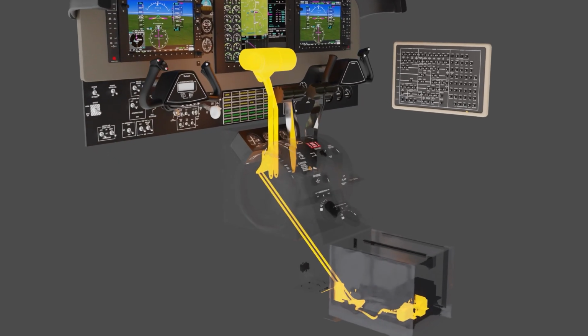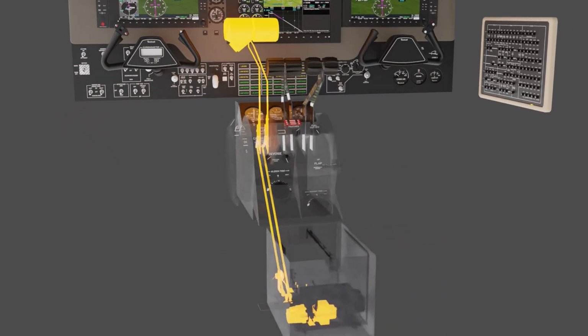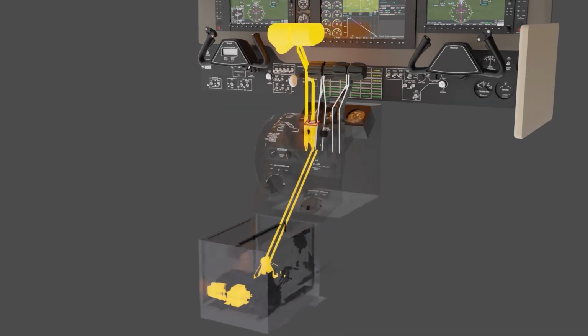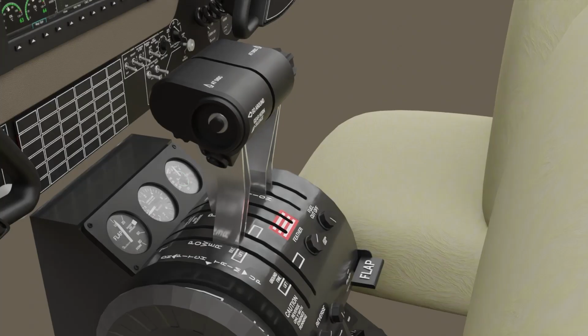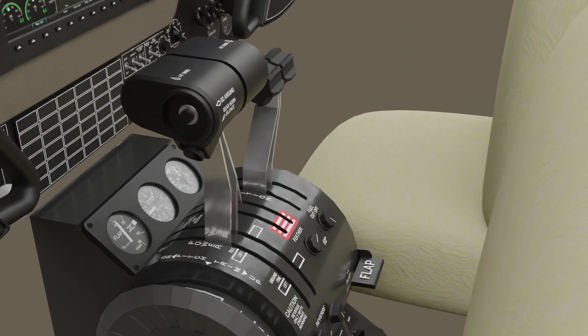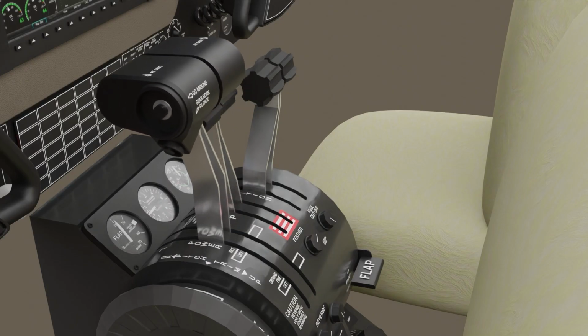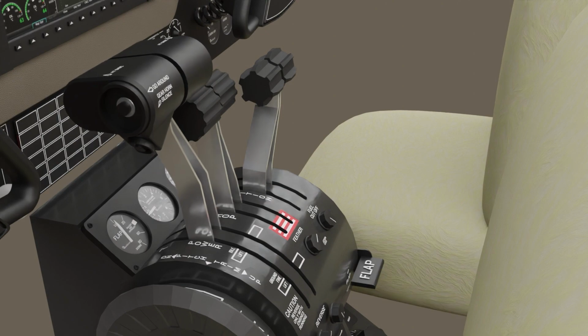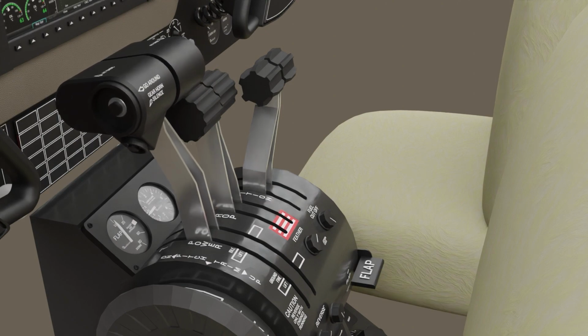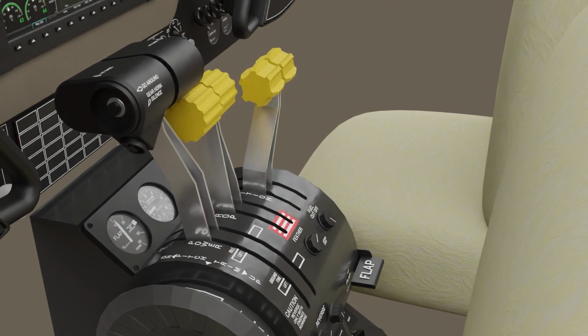The autothrottle system uses two independent servos to move the left and right power levers. The servos are located in the center pedestal and attached to the power lever control cables via a push rod. The servos can move the power levers from idle to max power. Autothrottle control does not include operations beyond the idle stop, in ground fine, or reverse. Propeller control and condition levers are still your responsibility.